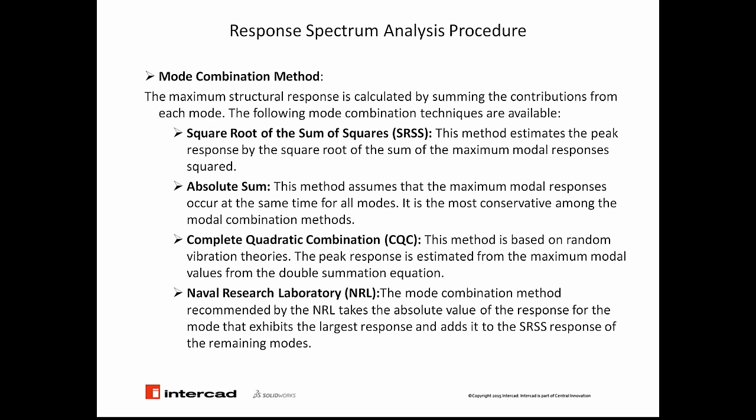The first one is square root of sum of squares, SRSS, which estimates the peak response by the square root of the sum of the maximum modal responses squared. We have different schemes, such as absolute sum, complete quadratic combination, and also Naval Research Laboratory. We can provide more information if you would like, but we are not going to spend a lot of time on the details of each.